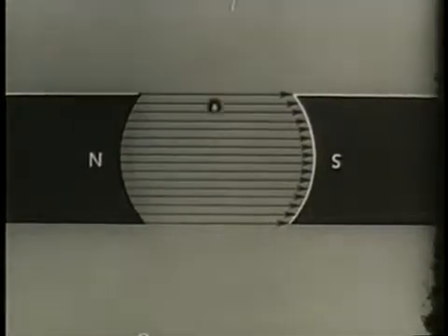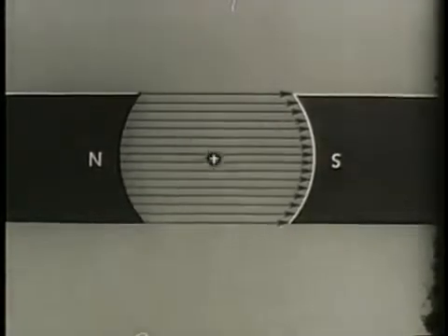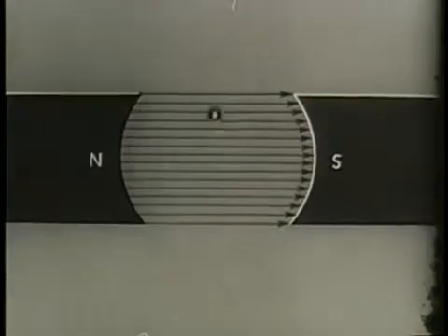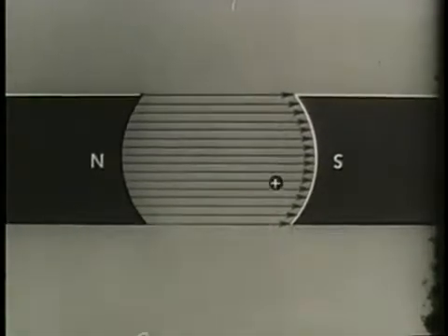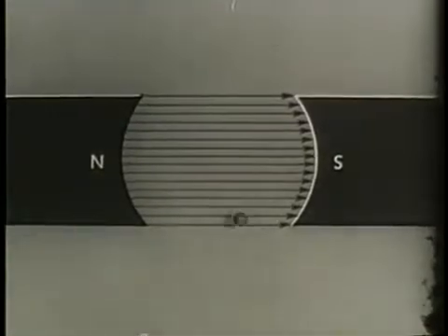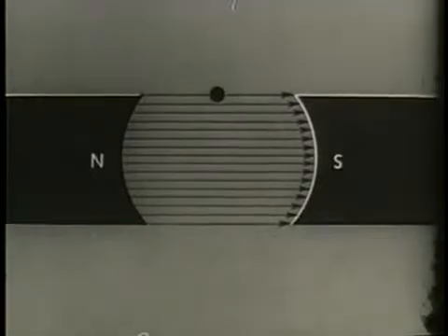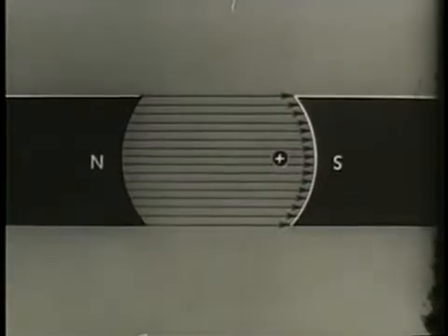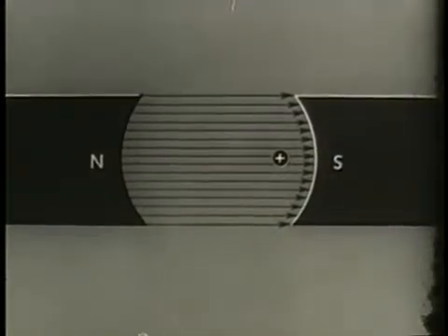But the conductor in an actual machine is not moving in a straight line, but rotating. When the conductor moves in a rotary path, the number of lines cut varies depending on the position of the conductor. At the top of the field, for instance, no lines are being cut and no EMF is generated. As the conductor keeps turning, the number of lines cut increases so that at a quarter turn or 90 degrees, the maximum number is being cut and maximum EMF is generated.